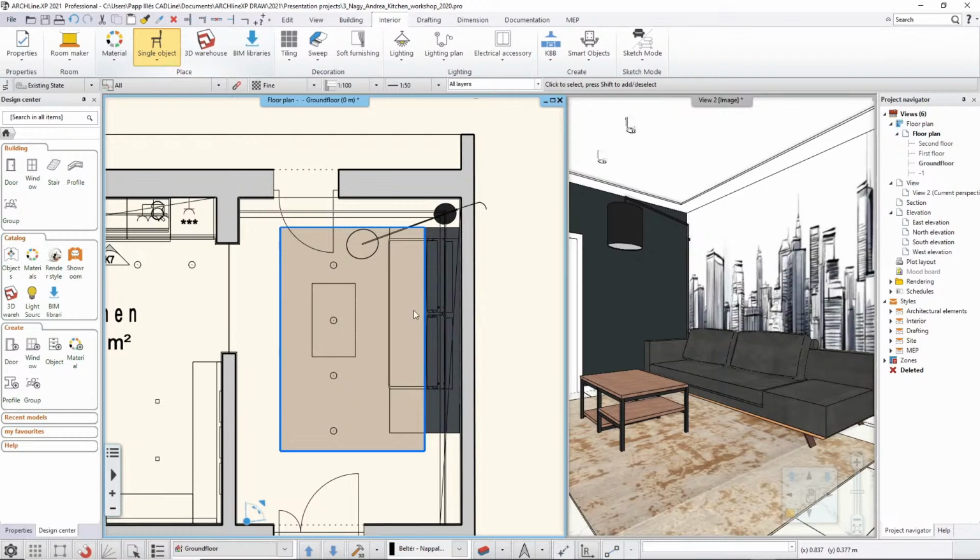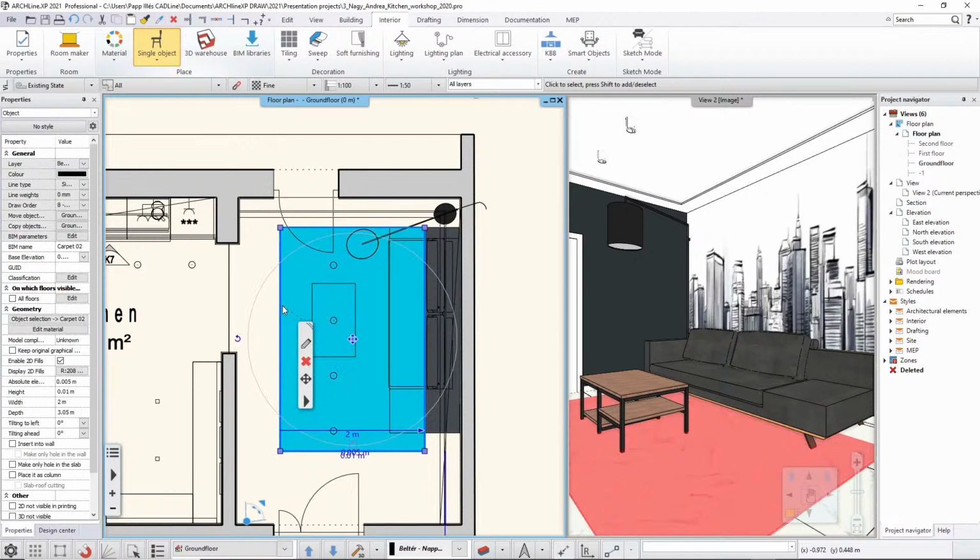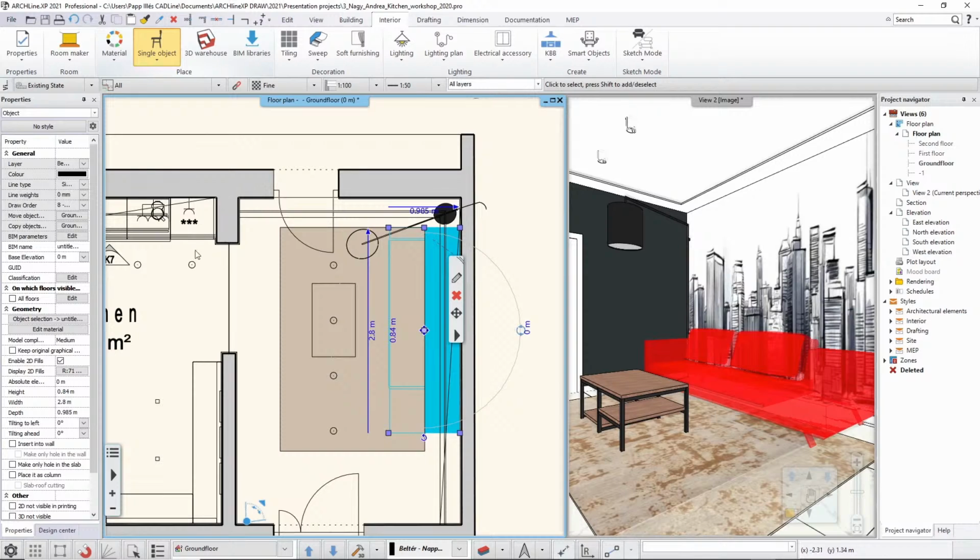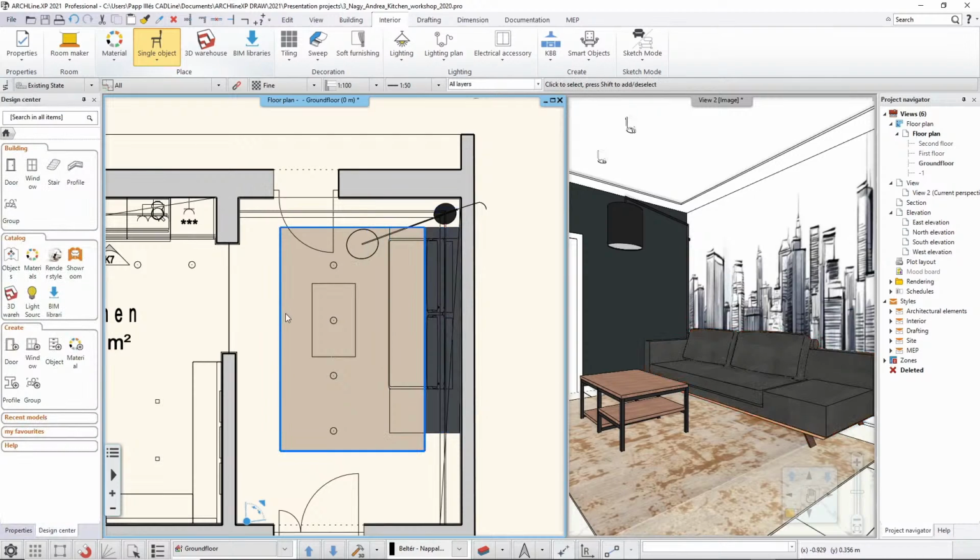Now the reason for that is that whenever you place an item in the 2D, it will automatically get an automatic drawing order, which in the case of objects is always the bottommost. It's always number 8. You have a 7 or 8 level draw order system, and everything falls to the bottommost. Now, as both of them are at the bottommost level, the software couldn't decide which one should overlap the other, at least with the 2D shape. So the latest changed overlaps the other one.